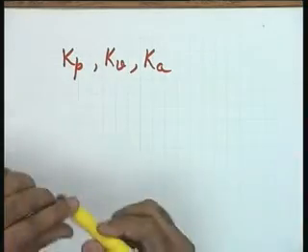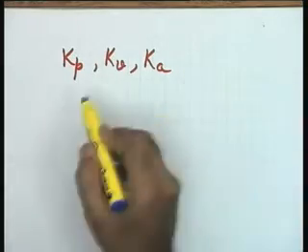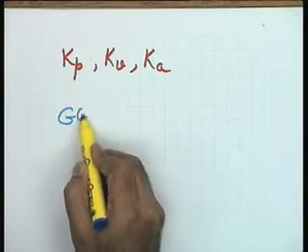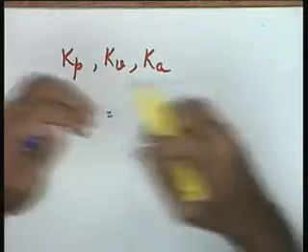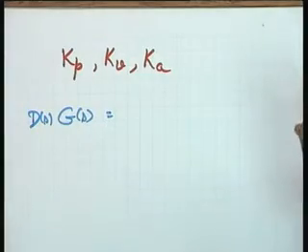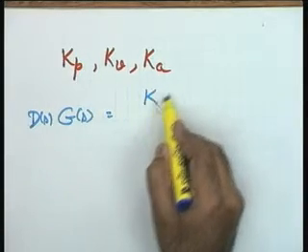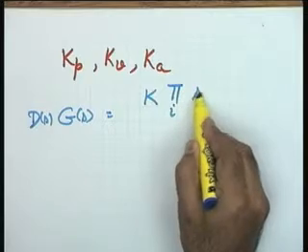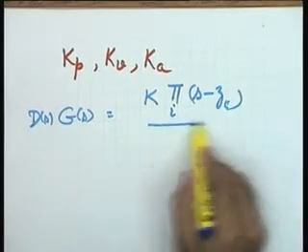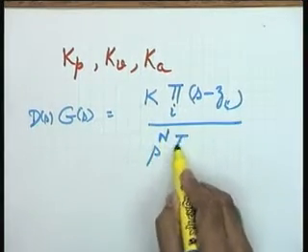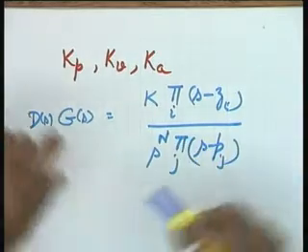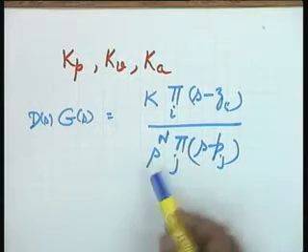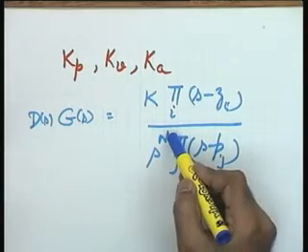One more point I want to introduce is the following. I have the relationships for these three. Let me look at Gs as a general expression. Gs or ds/gs. Why Gs? The total forward path transfer function now is dsgs with respect to the block diagram I have taken. I hope you won't mind if I put it in this form, product of (s minus zi) divided by s to the power of n times product of (s minus pj), where zi and pj are zeros and poles respectively, and s is also a pole at s is equal to 0 of order n.